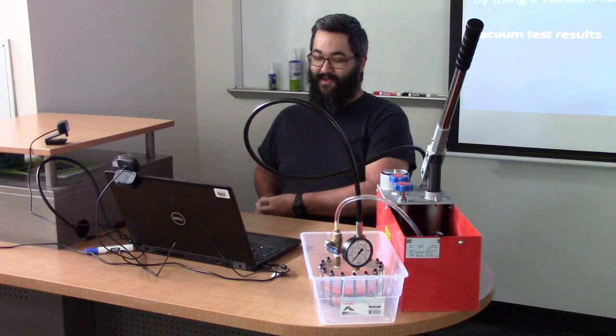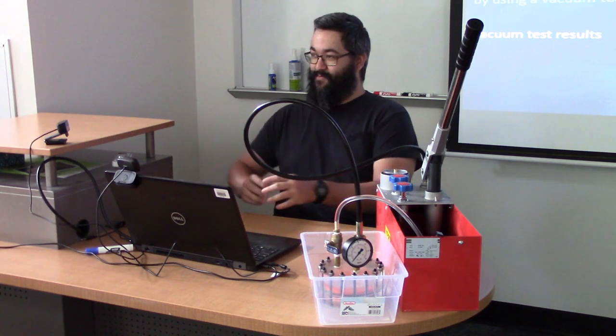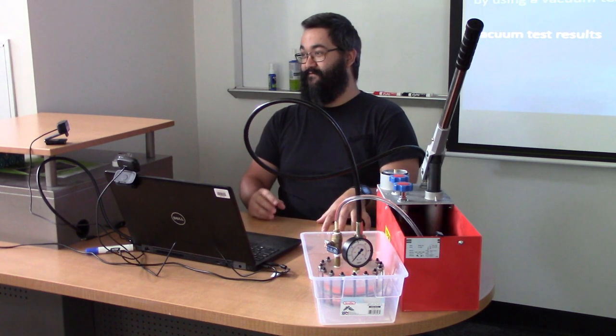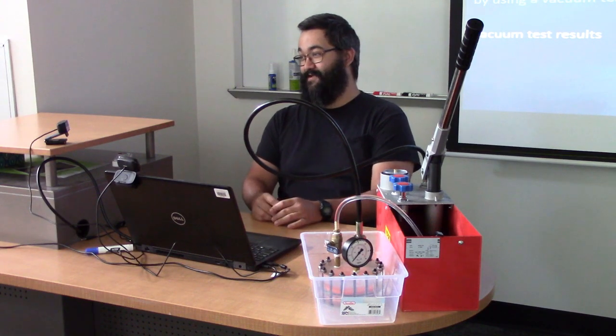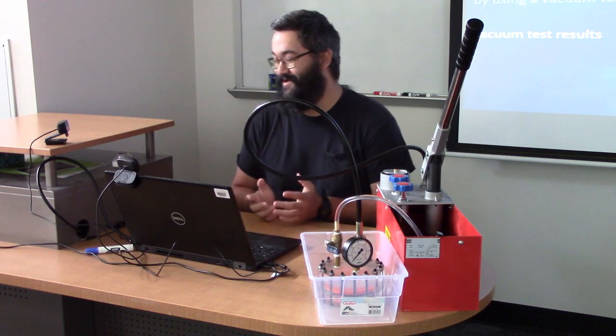Same thing if you're moving too slow and it's pushing out too much material at a time, it could also fail. So there's probably a sweet spot between the actual speed I'm choosing versus how much it's pushing out of the hot end. So of course that's even more testing that can be done to figure that out.